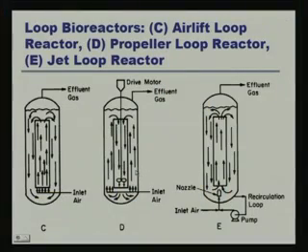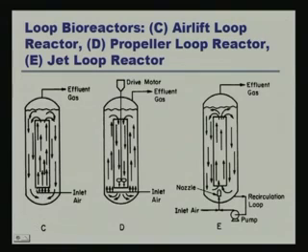Here obviously we can get somewhat better mixing efficiency, and the KLa value for dissolved oxygen is improved compared to the earlier one. Here, inside the draft tube, the air, oxygen, comes in and pushes the liquid. Here, not inside the draft tube but from the outside, air goes in and pushes the liquid, and through the draft tube it gets circulated again.